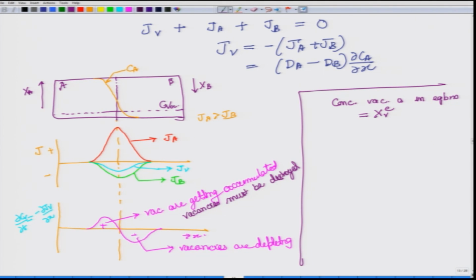Internally, not externally, the system must destroy the vacancies in some way or the other, and here vacancies must be created. Those will happen by movement of dislocations and also of the lattice sites. The movement of dislocations would lead, on one side, to creation of vacancies and, on the other side, to destruction of vacancies.